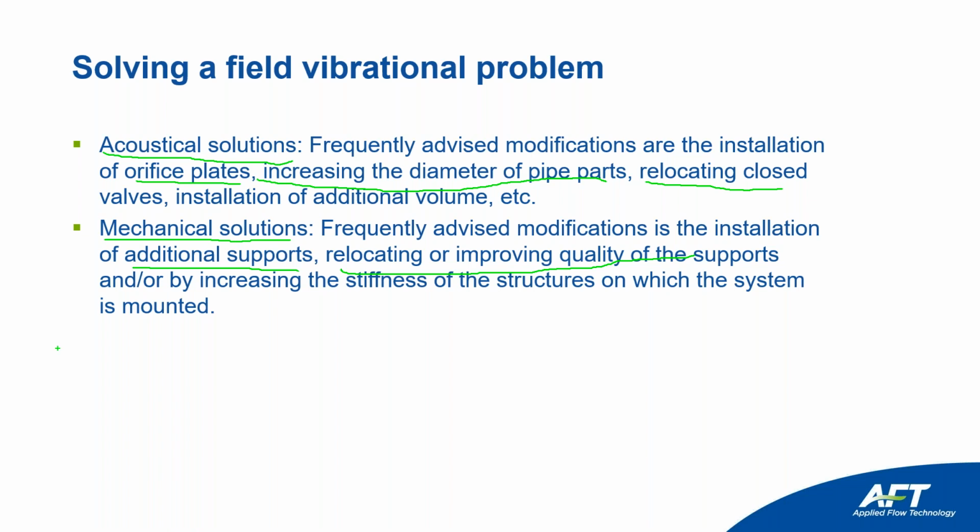so the low frequencies show up, which are generally the ones that require less energy to vibrate. And another one would be increasing the stiffness of the structure. Sometimes the supports are not strong enough, and although they're supporting the pipe, they cannot restrain it dynamically. So these are the solutions that you might find either for acoustical or mechanical problems.